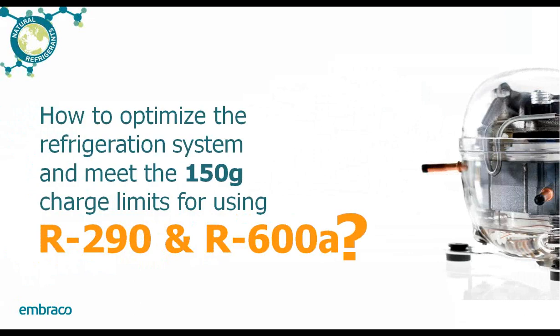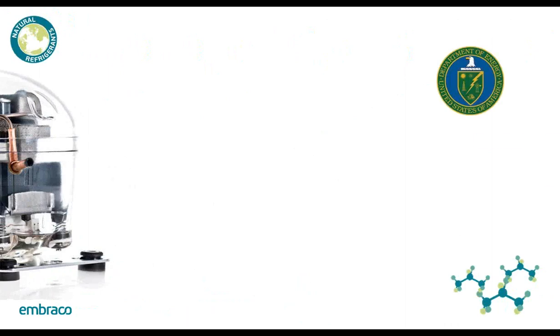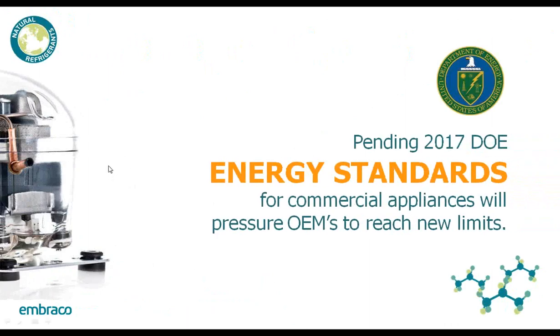What we're going to focus on today is meeting this 150 gram limit using R290 and R600a. First of all, the reason we're having this discussion is because of pending DOE energy standards coming out in 2017. These standards are extremely aggressive, some of the most aggressive in the world. And part of the solution to meeting some of these energy requirements is to use natural refrigerants like R600a and R290, which naturally give you better energy efficiency than R134a and R404a, which they are replacing.